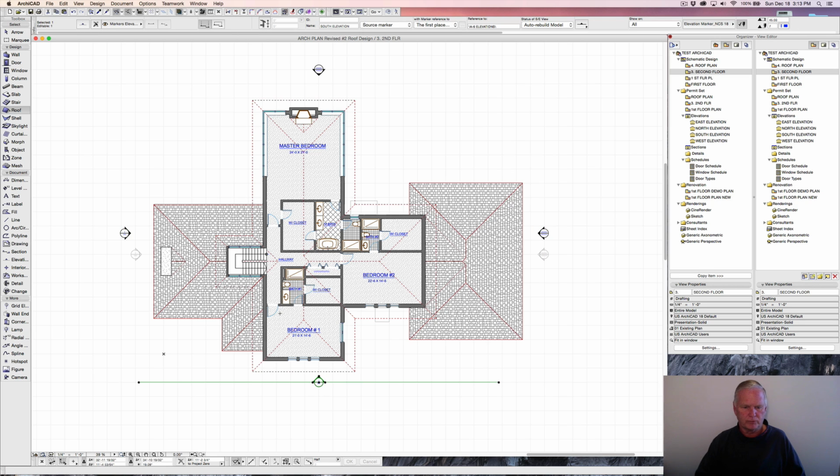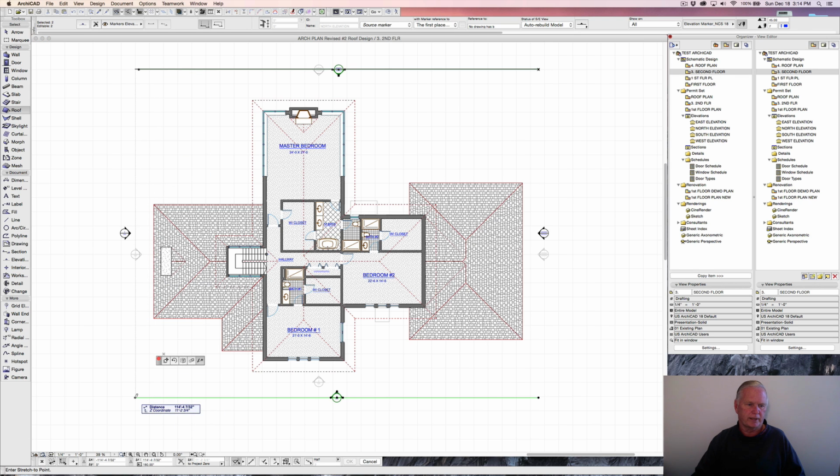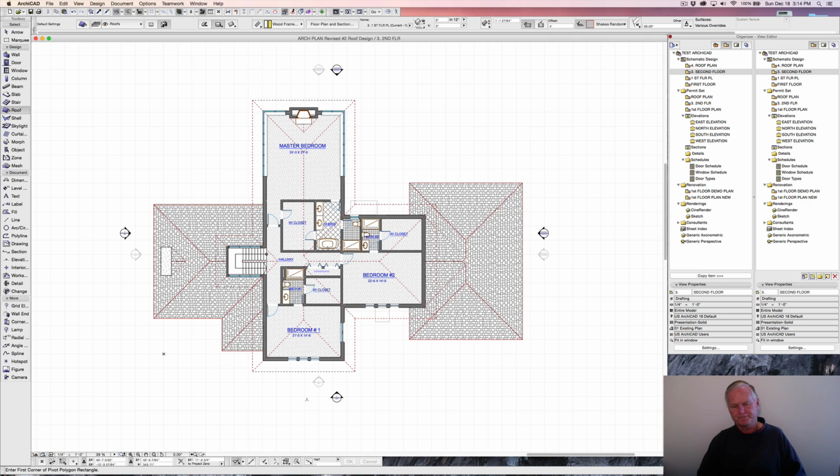We'll take what is going to be the front elevation marker, and go Control D and just pull it back a little bit to here. And then again, on the left side, maybe go to that grid line in line here, and we'll take it past here, maybe middle of this grid line. And then up above, that one's probably pulled away far enough, so we'll just highlight that with the other one highlighted at the same time. Pull this out and just drag it and make it match. And again, take the left side as we're looking at it, which is really the right side of the elevation, and click on it. And so now we've got the 4 set up correctly.